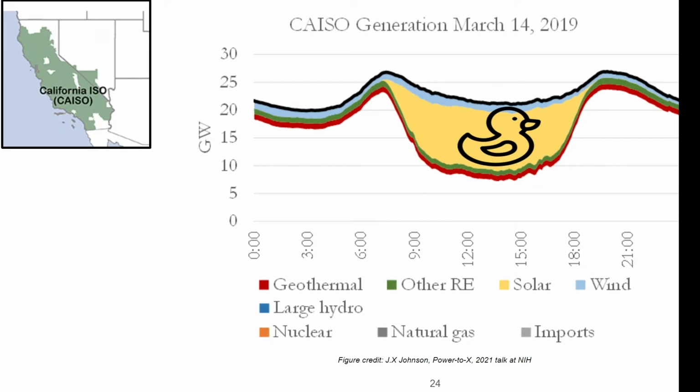What renewables cause on the grid today are these steep ramps in the evening. What's happening in the evening is that when the sun sets, your solar generation goes from 100, whatever it's operating at, to zero. And simultaneously, people are going home, they're switching on their lights. So your demand is increasing while a substantial generation that you have on your grid is decreasing all of a sudden.